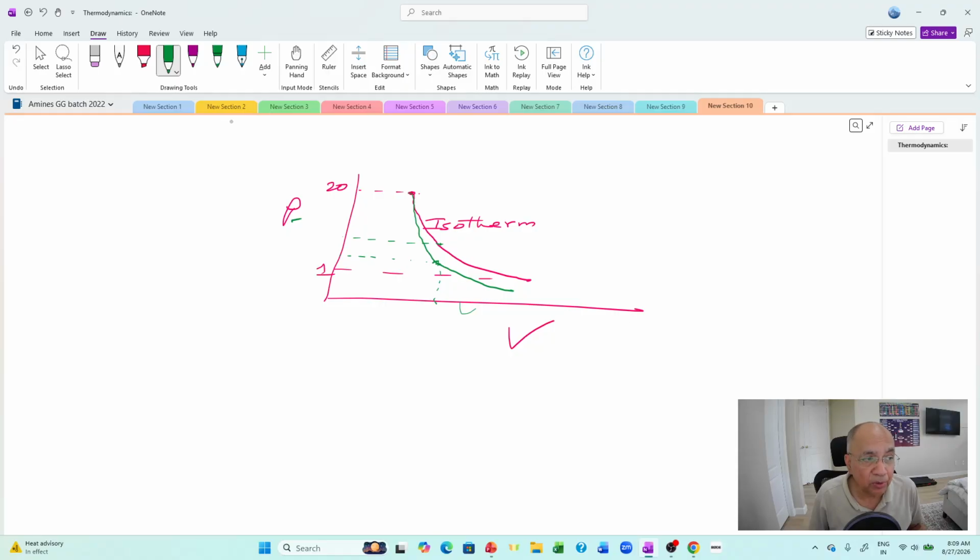So adiabat will have less volume at every point at constant pressure. If pressure is constant and you compare volumes, the adiabat will have a lower volume during expansion. And if you keep volume constant, then the pressure will be less in the adiabat, because the less the temperature, the less the pressure, there is cooling. So remember, this is the adiabat, which will be running below.